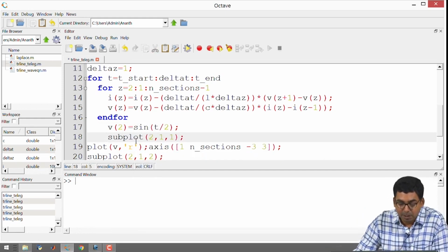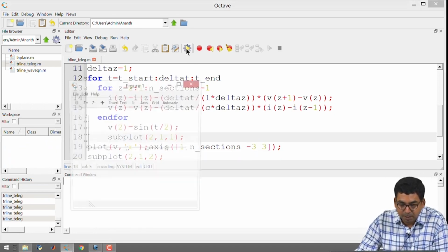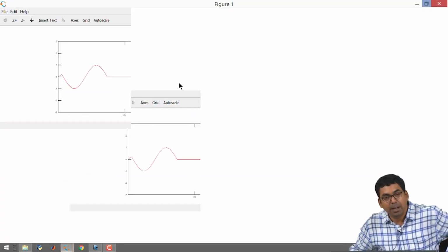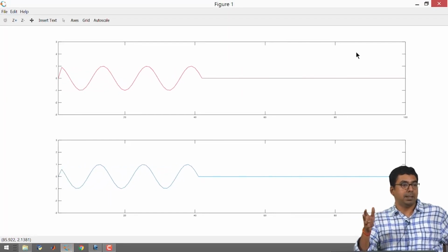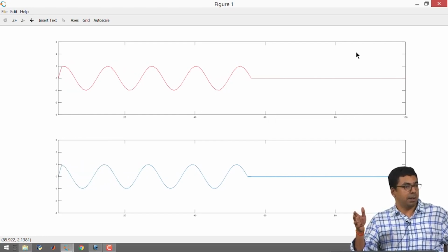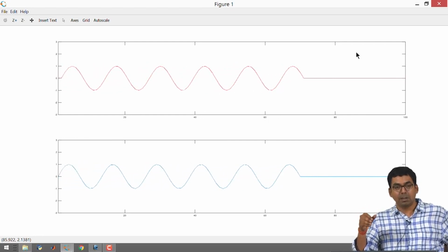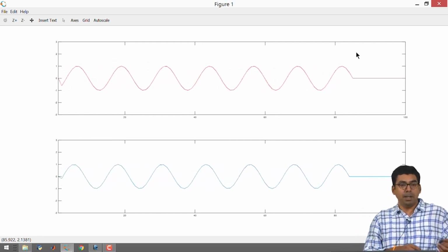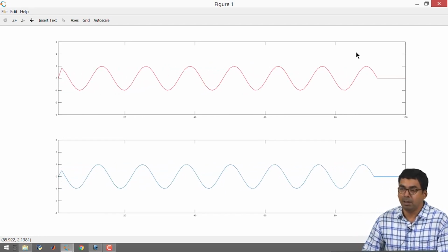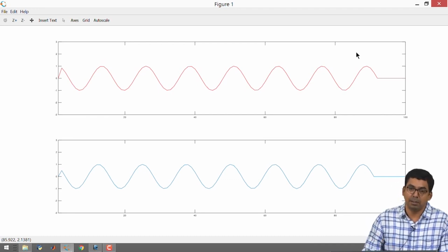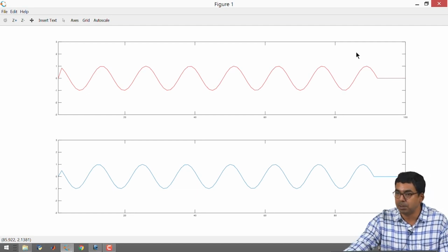So, I am just giving a sinusoidal input. So, you will be having a transmission line excited with a sinusoid, and we are going to make steady state analysis of this kind of configuration. And we will also be doing the same thing as what we did. We will be calculating characteristic impedance instead of characteristic resistance, right, and we will be calculating reflection coefficient, which will have signs positive and negative. On top of that, we are also going to see if it is possible to have phase for a reflection coefficient other than 180 or 0 degrees.